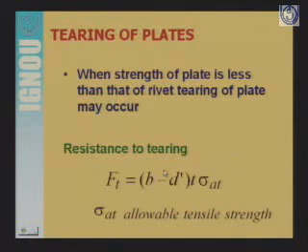Now let's talk about the tearing of plates. What happens, as I told you earlier, is that because of making holes in the plate for making connection, the strength of the plate decreases, and rivets are driven into these holes.